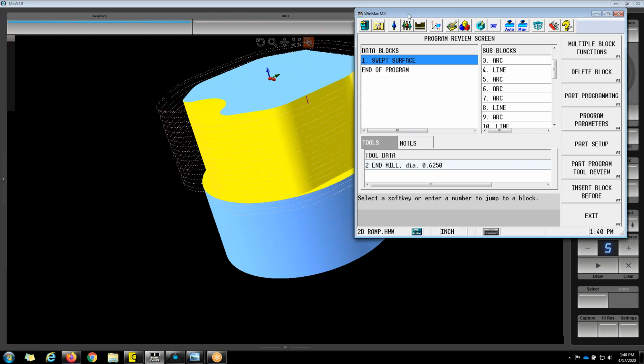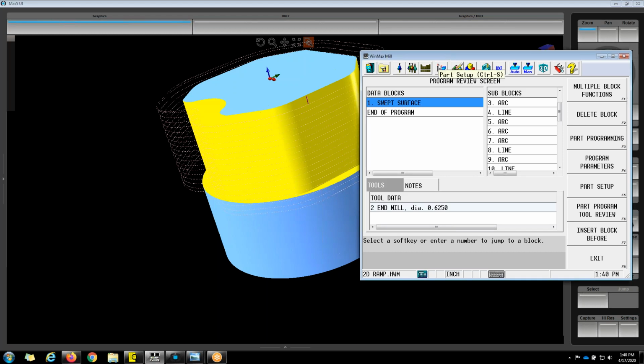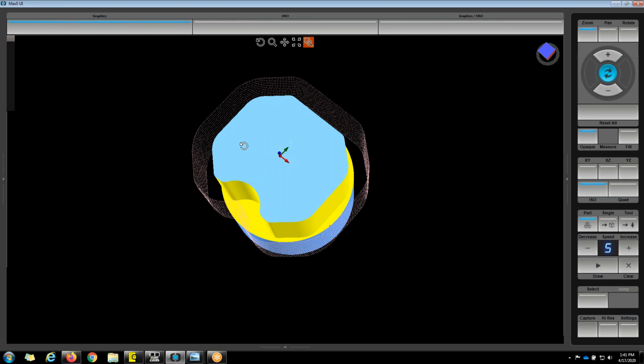If you wanted to use the helix, you could program these straight lines with lines and arcs, and then each of these radiuses you could use helix there as well. But at that point, since you're already doing the straight lines, you can just do about the same thing with an arc with a different Z endpoint. Yeah, short answer being that this particular shape wouldn't be very good for helix. Yeah, you could if you really wanted to put the effort in, right. But you're going to end up with a lot of time in something like that.